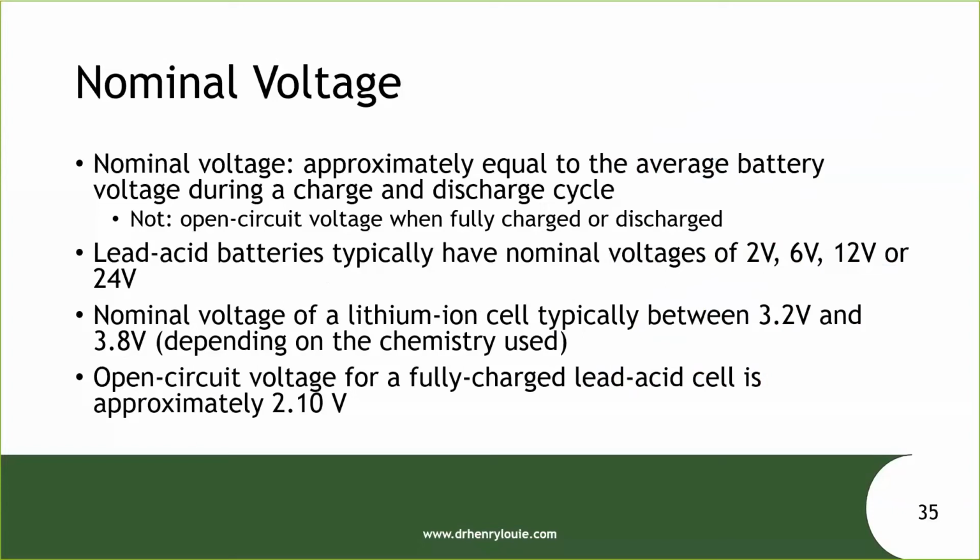And I think a mistake that a lot of beginners make is assuming that if I find a battery and its terminal voltage is its nominal voltage, then the battery must be full. And that is absolutely not the case. You need to look at the information provided by the manufacturer to understand how one might relate the voltage to the state of charge within the battery.